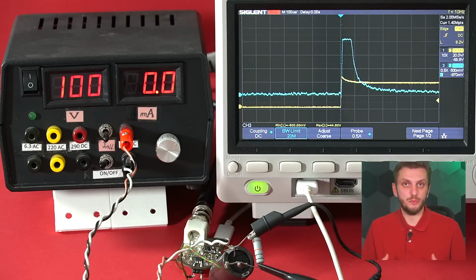So even when working with current limited power supplies, it's important to keep in mind that the output capacitors, once charged, will discharge with no current limit unless you add something in. So this is one case where extra current limiting circuitry might still be needed. Let's now continue by looking at the case of an inductive load.